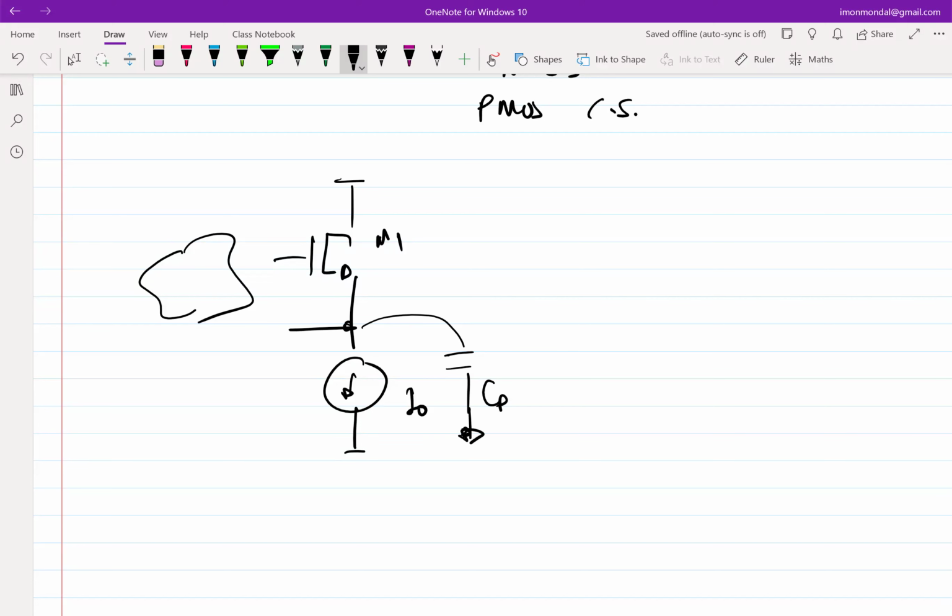So let's say I observed VS, the source voltage of M1, and we observed that VS1 is, let's say, increasing. So VS1 is increasing. What is the conclusion with regards to the currents? VS1 increasing means IDS1 is higher than I0, right? So the conclusion is, this implies IDS1 is greater than I0.